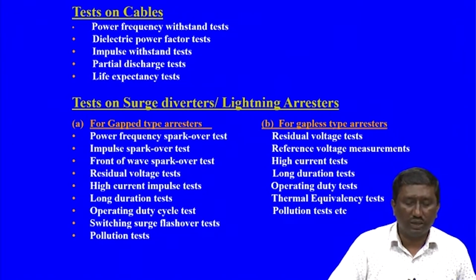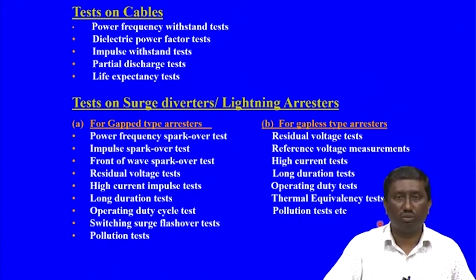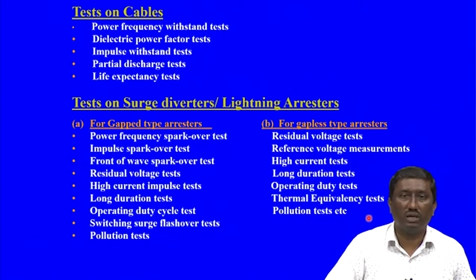Then life expectancy, that is how long the cable could be in service. So, there are again prescribed tests to estimate the life expectancy for the service. A suitable voltage and time with an acceleration factor is normally applied in the laboratories, and the life expectancy measurements are carried out.